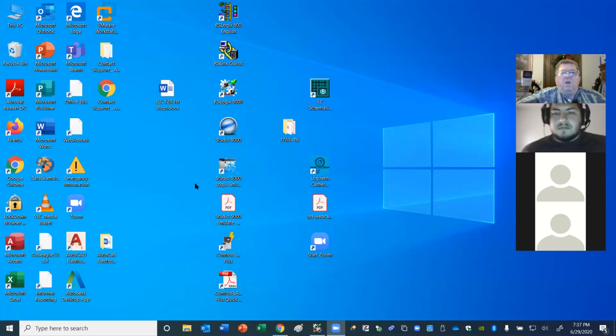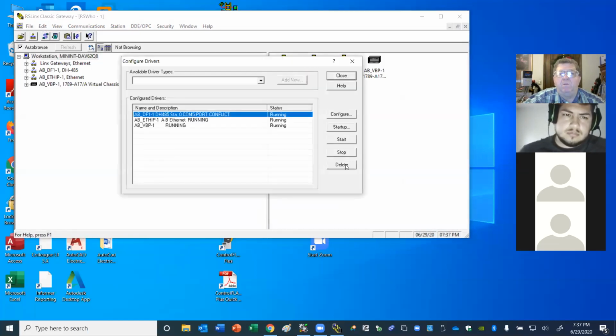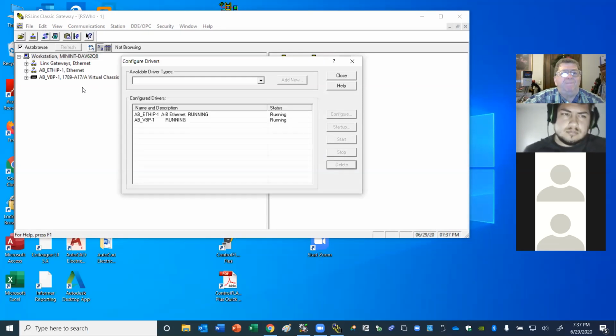Yes, sir. All right, now we're going to go up here to RSLogix Classic. RSLinx is the same Linx that we use for Studio 5000. It's just got all the drivers that you need for whatever kind of PLC you're dealing with if it's Allen-Bradley. So it's the same Linx. Do y'all see that Linx screen there? Yes, sir. Now I'm going to delete the driver that I just put in there because I've already set it up a while ago. Now, do y'all see my Ethernet driver and then the virtual driver?